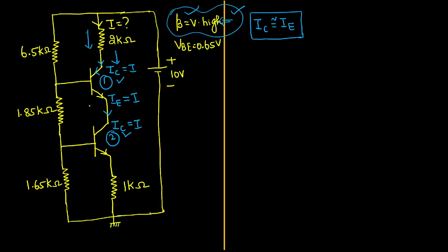Don't sleep. I'm just telling you, the first transistor is over. Now this emitter current is entering into the other transistor. In that transistor, the entering current is called the collector current. So this emitter current and this collector current are both the same. Here I am calling it emitter because for the first transistor this terminal is the emitter terminal, and for the second transistor I call it collector because this terminal is the collector terminal. Anyway, both are the same. Again, according to the given data, collector current and emitter current are the same, so the same I will be flowing here also.